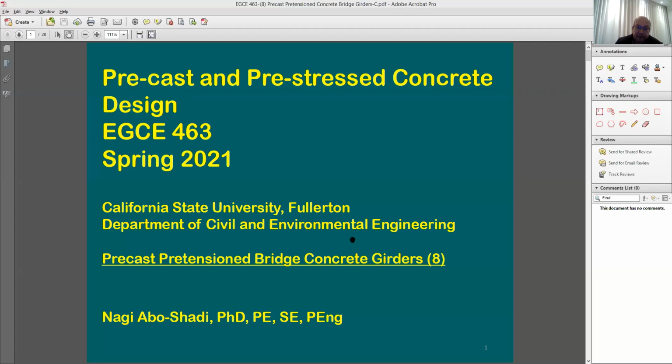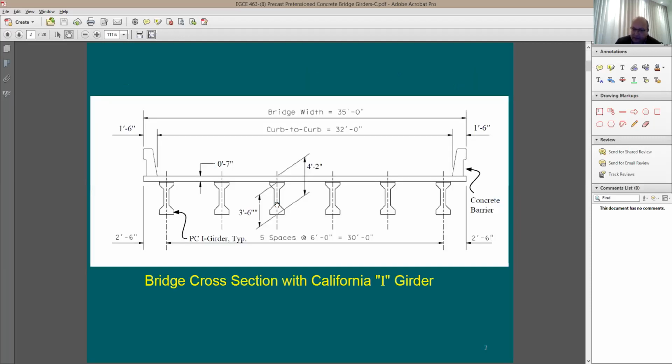Here's a new slide set, which is about bridge concrete design, bridge concrete girders, and the big difference between these girders and double T's, and just a different industry. You have design for parking structure beams and double T's versus residential buildings versus bridge beams and girders. The same information and the same design methodologies that we used for any other pre-stress beam or double T is going to apply here. This is just going to be a different designation and different sections, if you like.